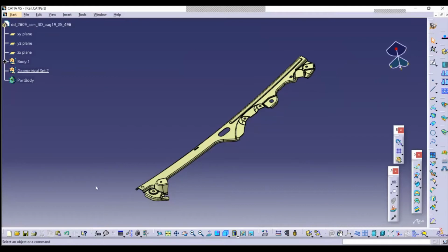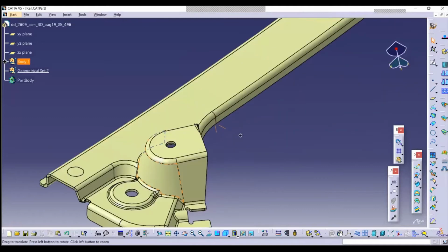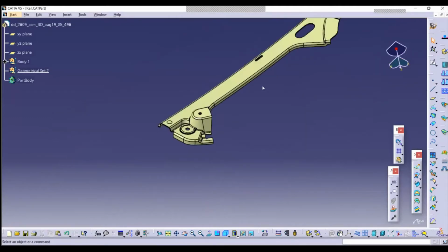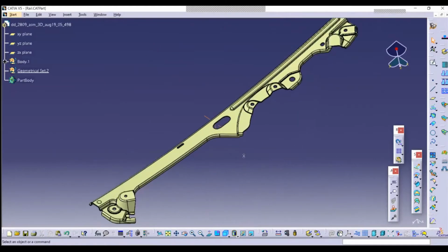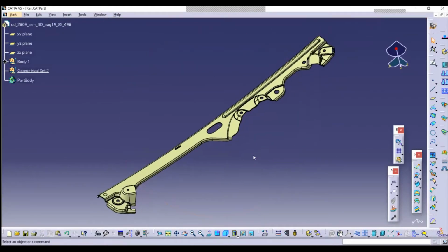In this case, I have a solid model, which you can see here. The way that we perform our analysis is we require a surface model representing one side of material. So what you'll see within the process is I spend a lot of time doing things within CATIA, so I'll be doing functions within CATIA in order to prepare my model for my analysis.